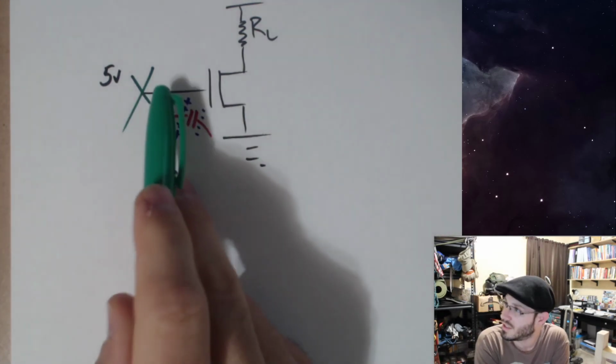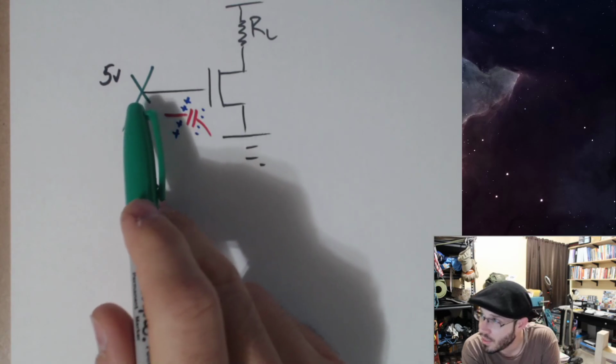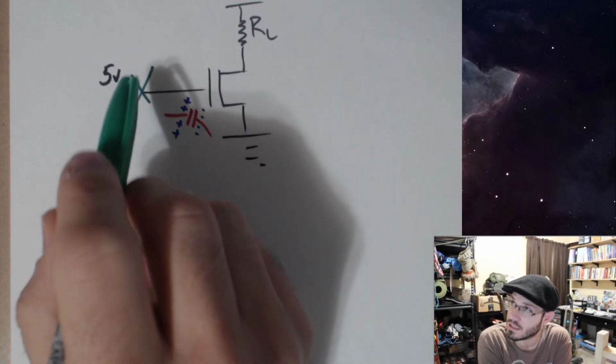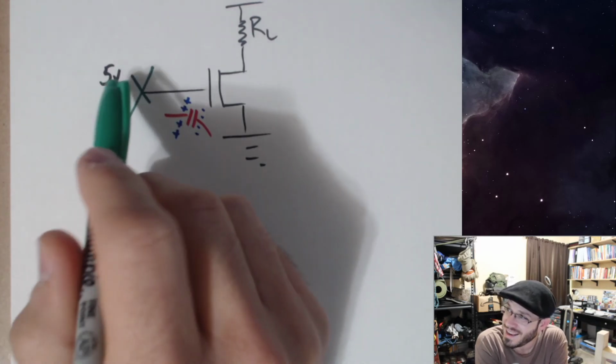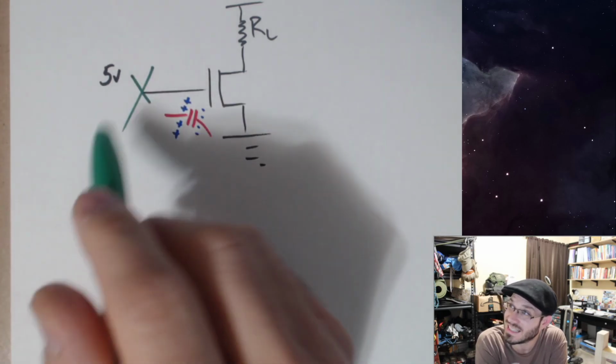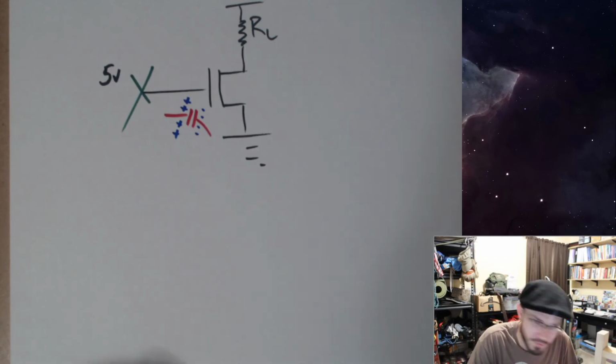So we lose the connection to the microcontroller, or there's also situations where, depending on the configuration of these digital logic pins, you may not have a strong path to ground in order to discharge. So we're talking about going from on to off of this MOSFET.